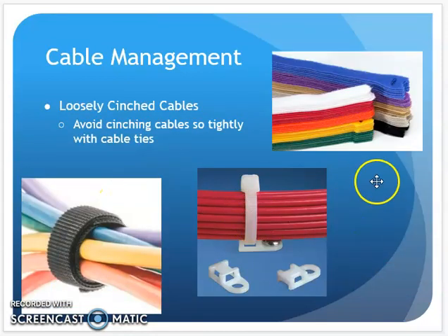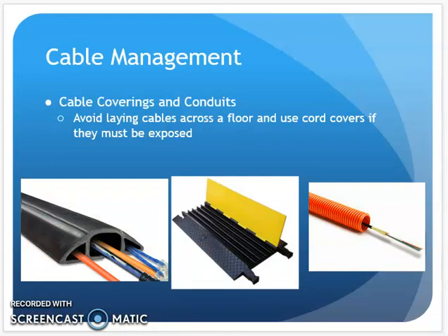When I'm bundling my cables, I need to really be careful of plastic cable ties. If I use them, I need to bundle them loosely. Better yet, I should be trying to use the Velcro cable ties. Those I can undo and loosen up, so I don't have them bundled too tight. In many cases, I can undo these, lay more cables in, and then put them back around. That's usually the better route to go, the Velcro cable ties. But I need to make sure they're not bundled too tight.